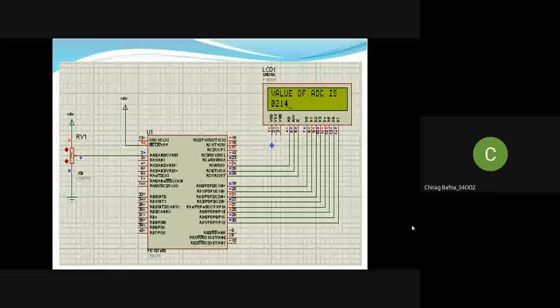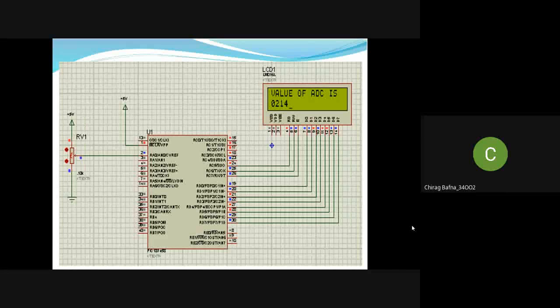Many data acquisition applications need more than one ADC. For this reason, we can use an ADC chip with 2, 4, 8 or 16 channels on a single chip. Multiplexing of an analog input is widely used, as shown in the figure. In this chip, we have 8 channels of analog input allowing us to monitor multiple quantities such as temperature, pressure, heat, and so on. PIC18 microcontroller chips come with 5 to 15 ADC channels depending on the family member.